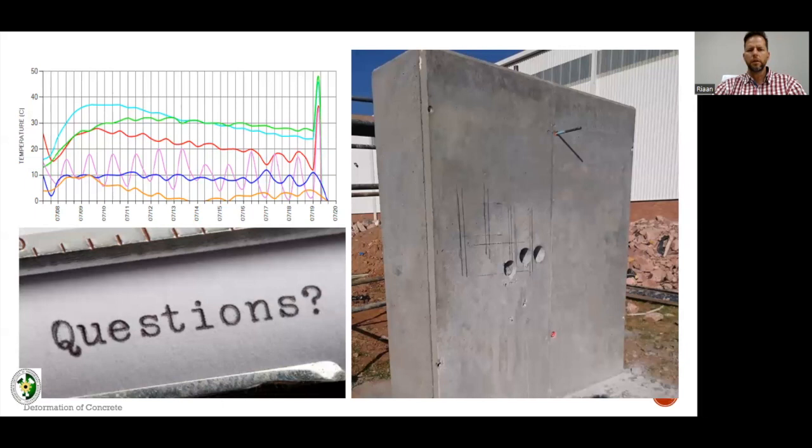Rowan, dam shows the white seeping through. What can be done, or does the service of the dam come to an end? Now, there's nothing you can do, because with a dam, you know that the inside of the dam is full of water. So the process would be, firstly, to establish the level of damage and how far it's gone, to establish whether your structure is still competent, whether it is able to withstand another year, another 5 years, another 10 years, before it becomes inoperable or unserviceable or unsafe.